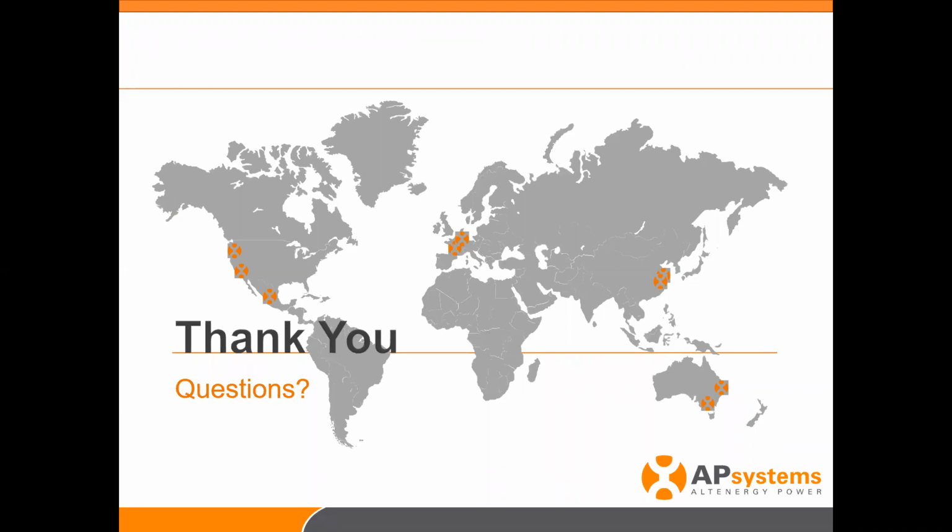Okay, Jason, I see one just coming in here. A good question, actually. Can I add a YC600 microinverter to my old ECU and mix it up with other YC500s? The answer is actually yes and no. So you electrically can put YC600s and YC500s on the same house, on the same lines. They will produce power all day long. What you will require is a new ECU to communicate to the YC600s.